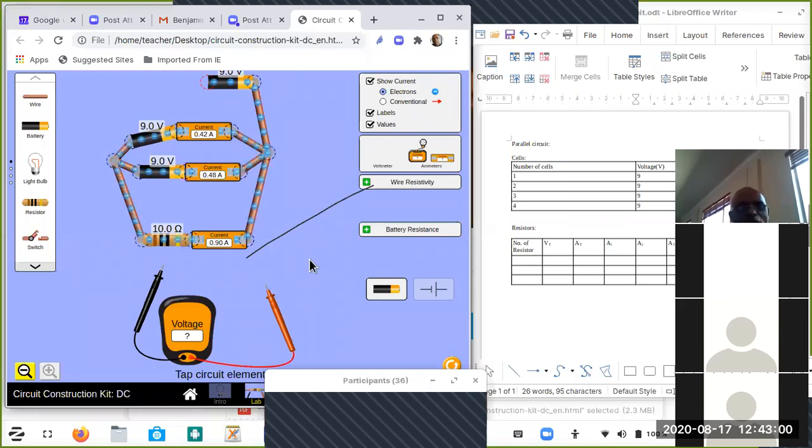Thank you so much. Now, whenever we are having cells that are connected in a parallel connection, what happens here is each cell is producing its own current. So the sum of the current of the cells that are connected parallel to each other will add up to the total current flowing through the resistor, right? So that must be known. So we are having two pathways, which simply means the total current flowing through the resistor is distributed or shared among the two pathways, right?